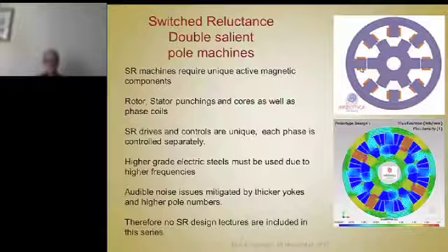Then you fire the next one, and you have this again on the next pair of poles. Now the one below has four attracting points, 90 degrees apart. So instead of trying to make itself elliptical as it is commutated, it becomes more like a square. Just on the face of it, the one at the bottom is quieter.